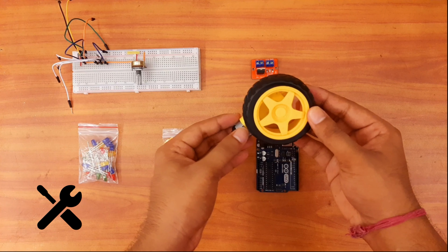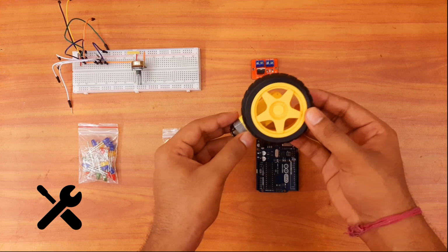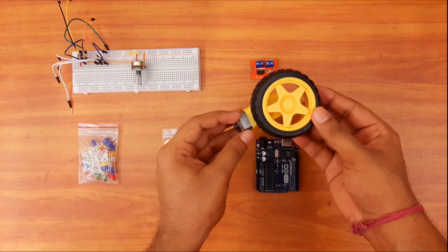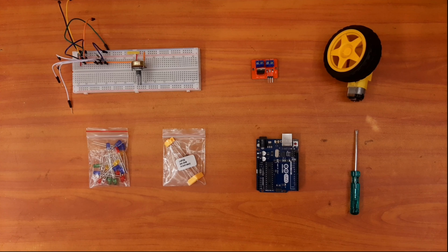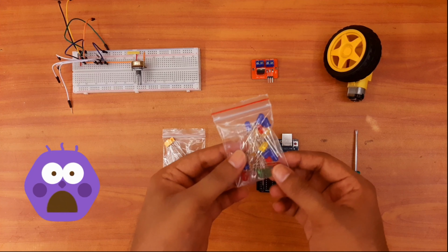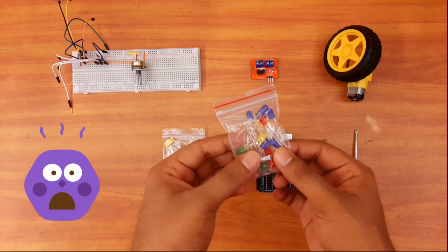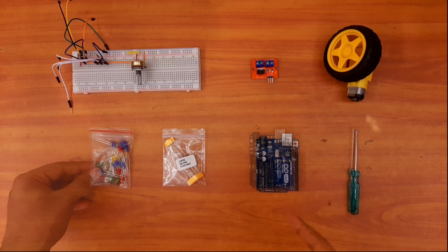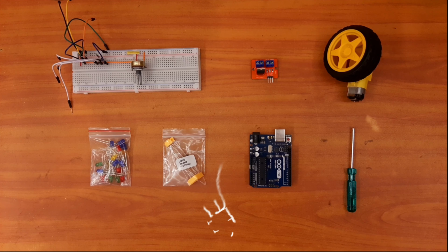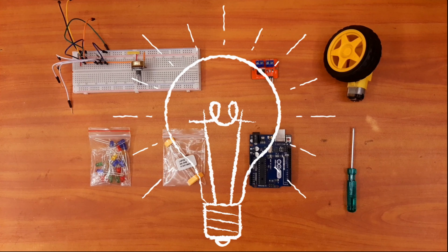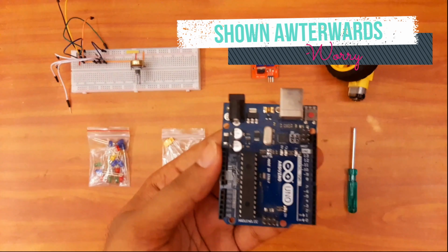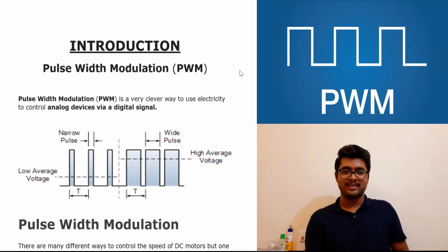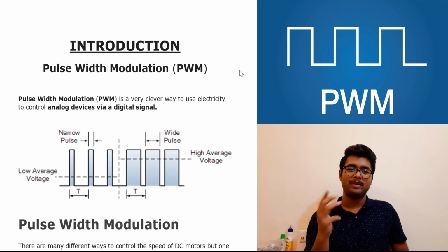In digital electronics, we basically use the high and low concept, where high indicates plus V voltage and low indicates 0 voltage. Neither can you control the brightness of these simple LEDs using the rheostat concept with the Arduino. Now to solve this problem, we introduce the PWM concept in digital electronics. In the previous video, I clearly showed you the PWM pins in Arduino. Now friends, let us understand what PWM is.